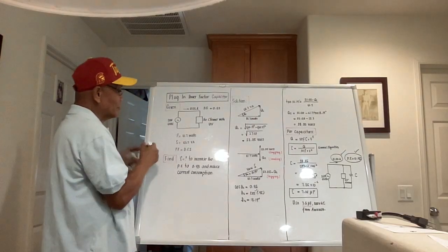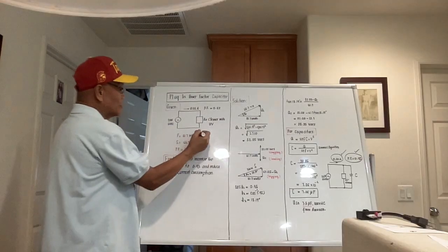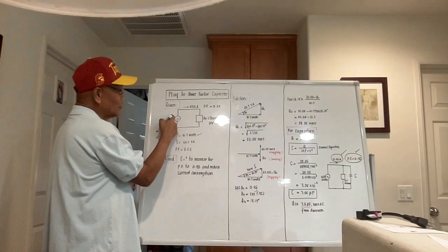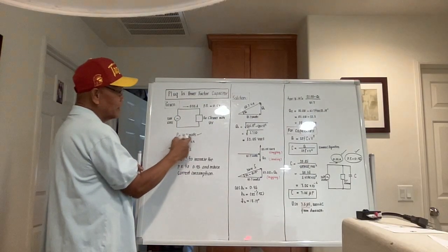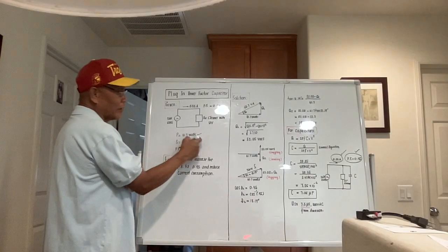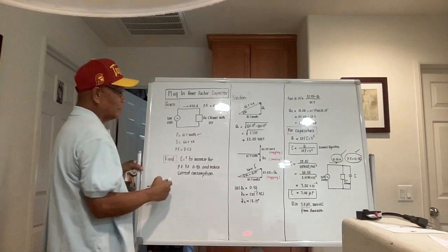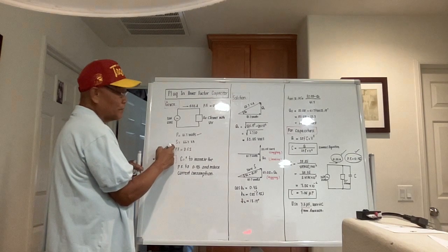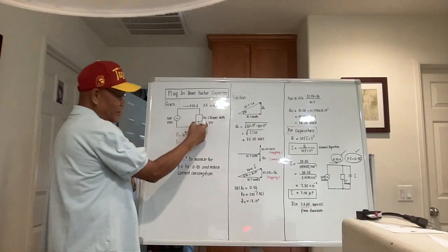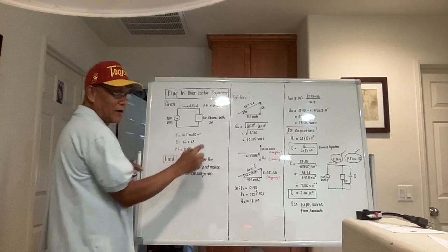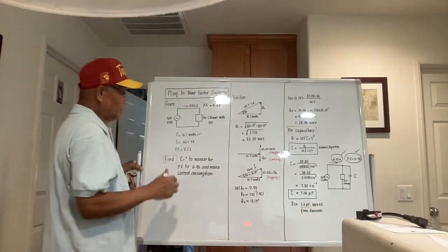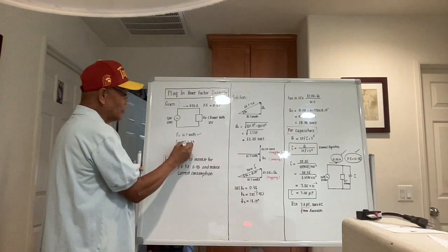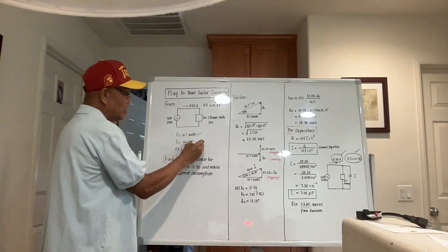The true power consumption is actually 41.7 watts. If we operate this one on 120 volts and 60 hertz, the true power, the wattage, is 41.7. Capital letter S represents apparent power. What comes out for this one is 66.7 volt-amperes. This is now a real example, okay? And the power factor is 0.62. If you notice this 0.62, this is very low.